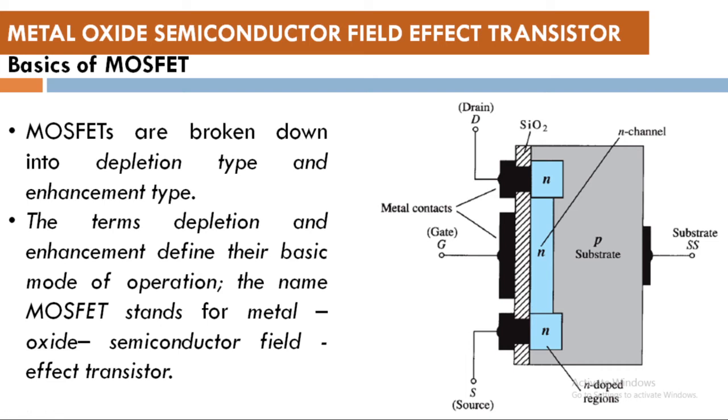This is a dielectric, and a thin layer of silicon dioxide is formed over this, and then certain techniques are used to remove this section and join with a metal contact, usually shown here by a black layer, to the respective regions, that is the drain and the source. With the metal contact we have a terminal called D, and with the metal contact we have a terminal called source.